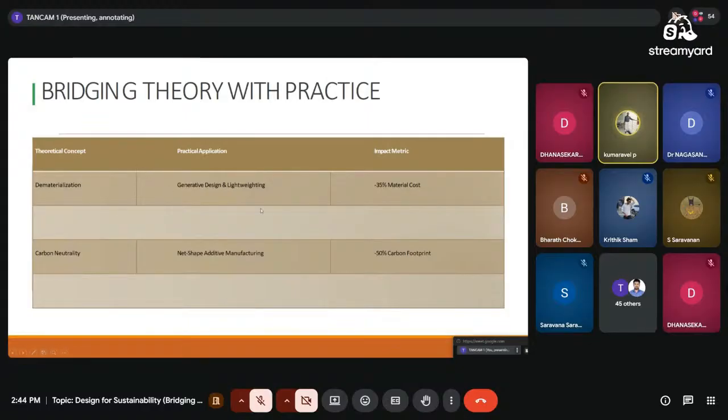So what we are going to do is use generative design. That means we will be creating an outer shape design. Once the shape design is created, we have to find out where the weight reductions can take place, where there are unnecessary parts or unnecessary platings. For example, in a back panel, there is a covering, one plastic plate, around 15 grams. We'll make it a mesh. Our mesh plate will be around 5 grams only, so we can reduce the weight by 10 grams. Like this, we'll reduce each and every weight so that we can produce a weight-reduced material.